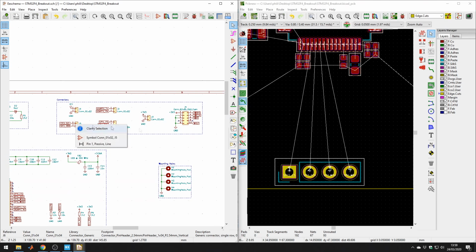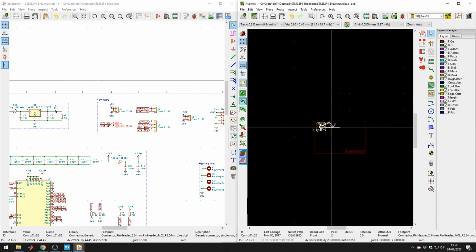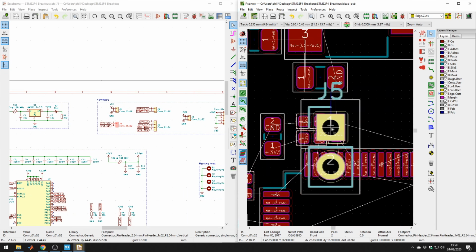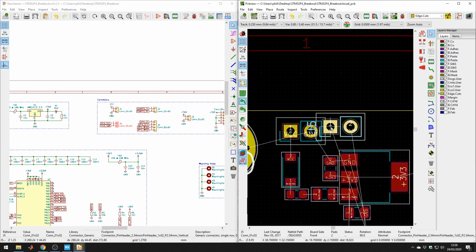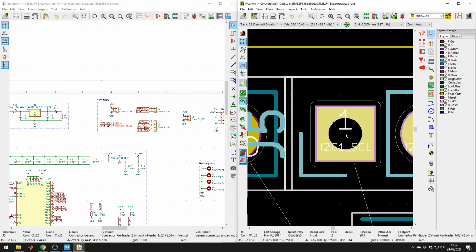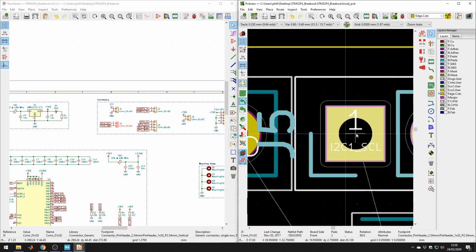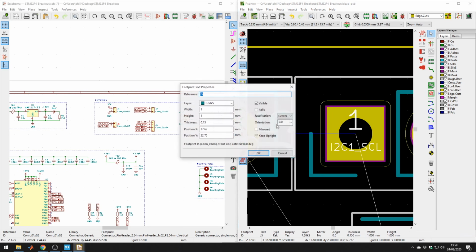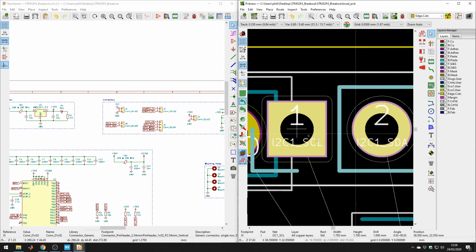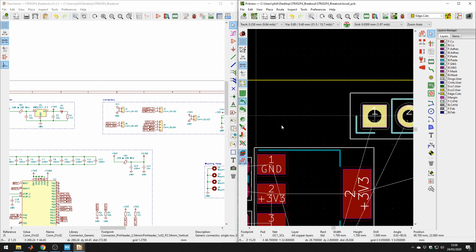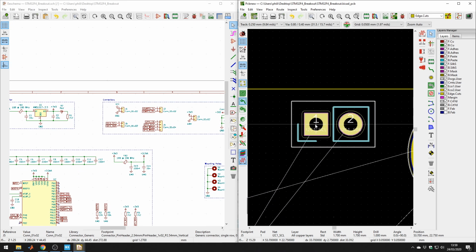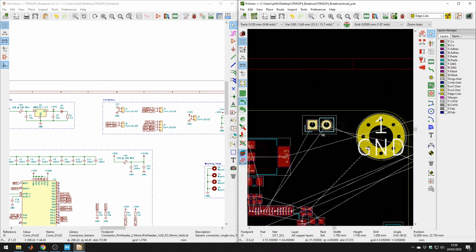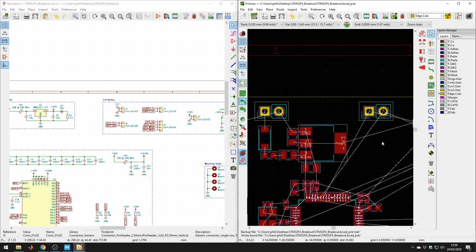What else do we have? I2C. So I2C, I will move up here as well. And you see how I'm aligning it? I'm just lining it up like this, right next to the other connector, which I know is in a good place. And then if I press M again, I can see these little guidelines, which will help me place it along the same height. And I'll put it somewhere here. You don't want to put it too close to these mounting holes either.